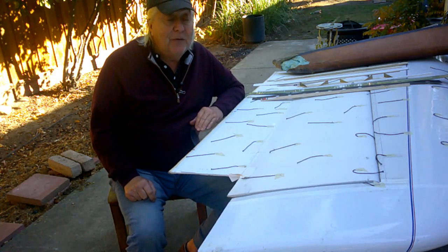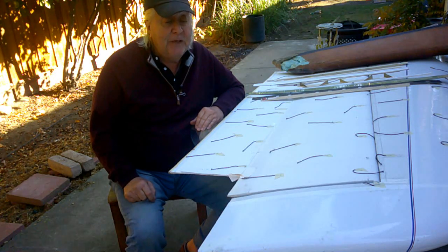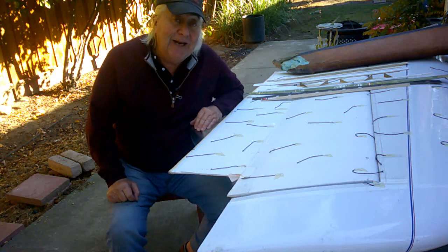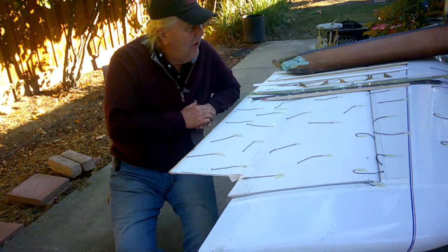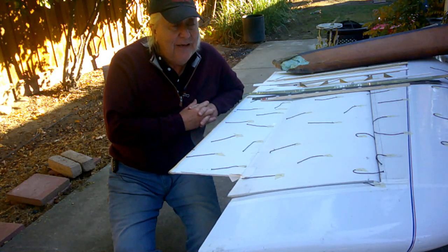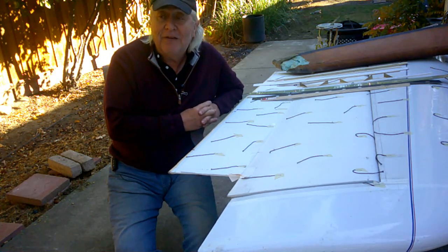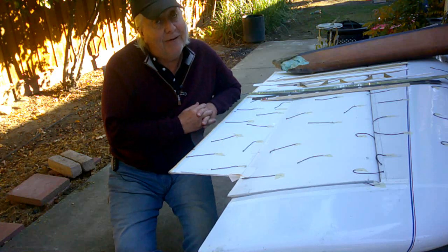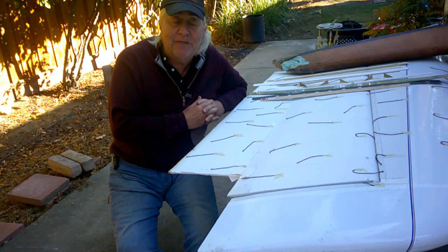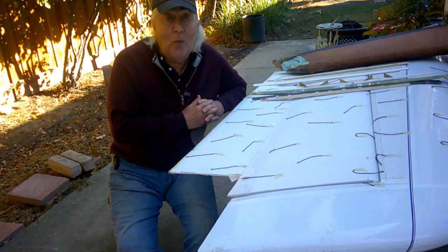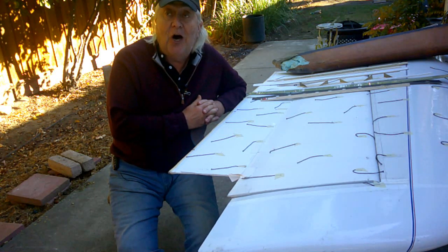So really not like my original design, and so pretty small tip, low Reynolds number. I go, how much of a problem could that actually be between 500 and 400,000? Is this really a problem? There's other hang gliders out there operating, and the Reynolds number diagram we looked at, well, hang gliders operate in that range all the time. How come they don't have a problem? They don't have elevons. They're not deflecting an elevon down. They're not experiencing the separated flow. In fact, on hang gliders, it's wing warping. And even more special about hang gliders, it's wing warping up only.